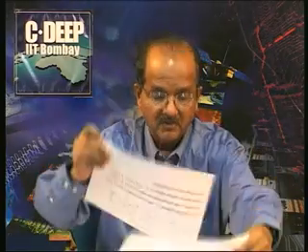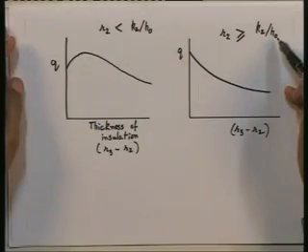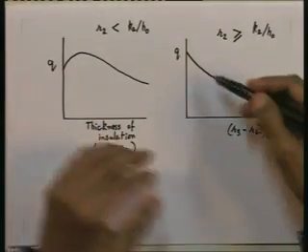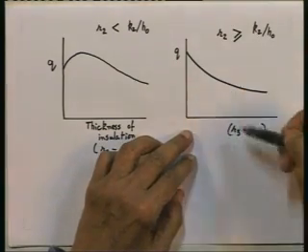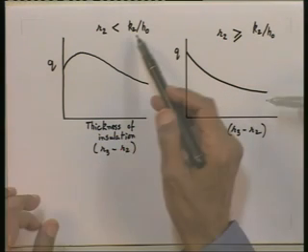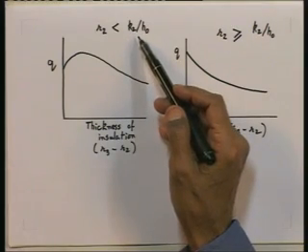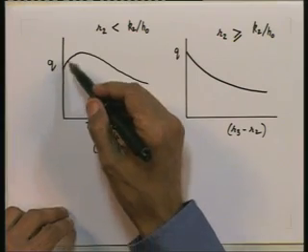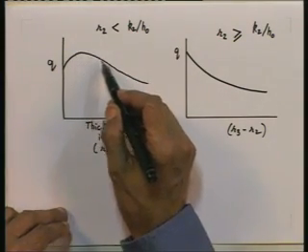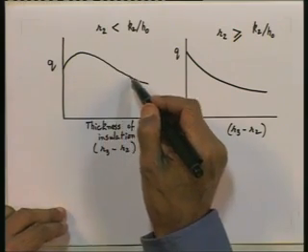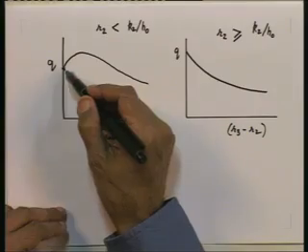So, when we put insulation on a pipe, the lesson to learn is, you want Q to go down. So, make sure to start with that your value of R2 is greater than or equal to K2 by HO. If this is so, no problem, whatever the thickness of insulation you put given by R3 minus R2, it will help. If on the other hand, you have a situation in which to start with R2 is less than K2 by HO, then what should you do? You must put enough insulation to see that you have crossed this hump and you have reached a point where the value of Q is less than the value you get to start with when there is no insulation.